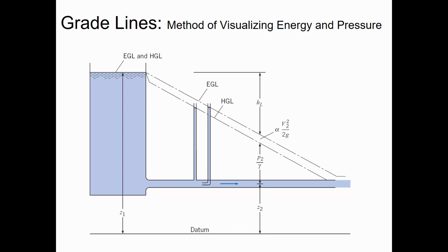We've talked about this before when we were discussing pitot tubes. There's a stagnation point at that opening, and it's pushing the water a little bit higher. And so now, when you face the opening of the tube in the direction of the flow, then the water level is going to rise to the energy grade line rather than just up to the hydraulic grade line. So we can get a physical idea of either the HGL or the EGL depending on how we connect some sort of a monitoring tube into the pipe.